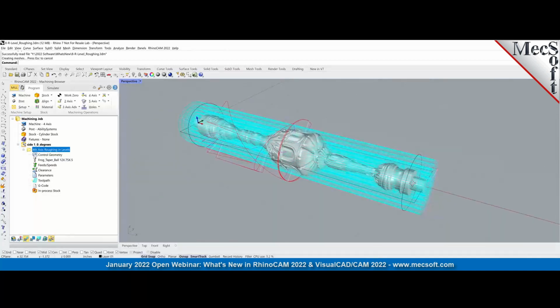This can be very useful for stability reasons of your machine tool. Instead of running the tool up and down for roughing, this locks the rotation angle to a certain angle and does all the machining. So you can see the toolpath. Let me run the simulation and show you the different levels. Is it cutting there? So that's one onion level, if you will. And then you go down on this side, you're cutting on the outside.